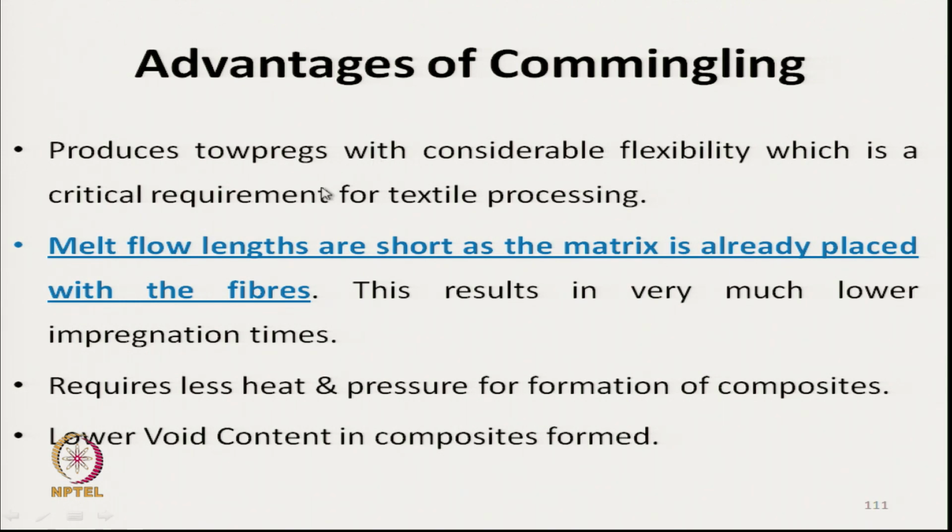As the matrix materials are present within the reinforcing fibers, melt flow lengths are short. So, this results in much lower impregnation time, immediately the reinforcing fibers get impregnated.